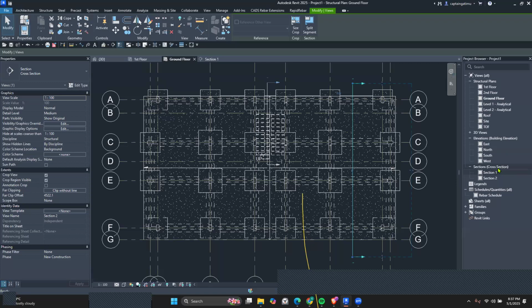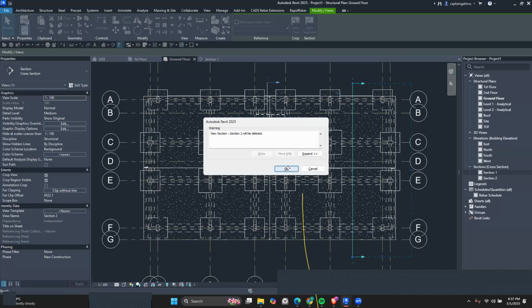For my columns, I want them under one category. This might look like a lot of work at this point, but trust me, when it comes to plan and production, you'll see how it makes your life a bit easier, since when you want to transfer something to the paper space, you can easily know where to look for it.